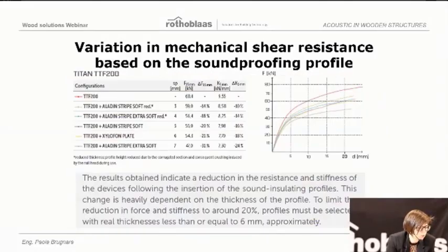And according to this, we have noticed that the thickness of the material will influence the static performance of the fastening system. We have seen that having a resilient profile will not affect the final connection too much if the thickness of the profile is 6 millimeters. If we have 7 millimeters, the decrease of the static performance is quite high, and for this reason we have chosen a very stable material that is only 6 millimeters thick.